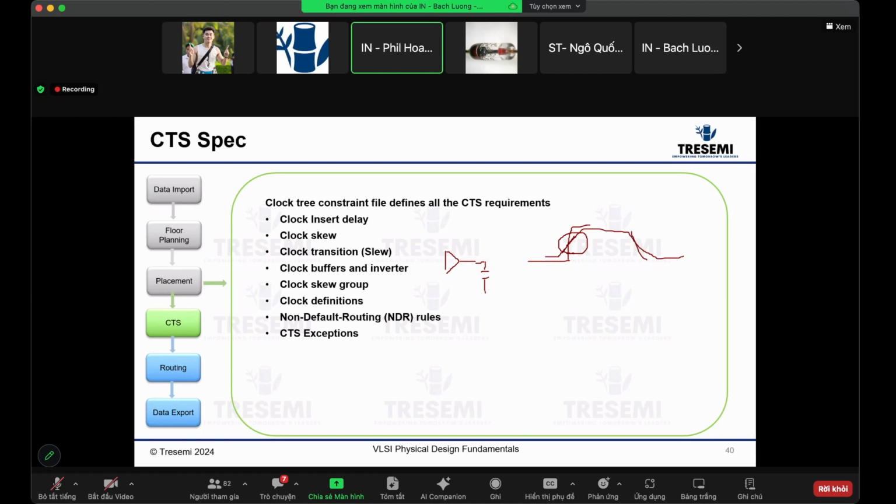To help with the skew, you want a little bit sharper rise and fall. It's a complex trade-off, and sometimes it's just understanding what your circuitry is like. You can make the right choice in terms of the width and the spacing between the clock edges.